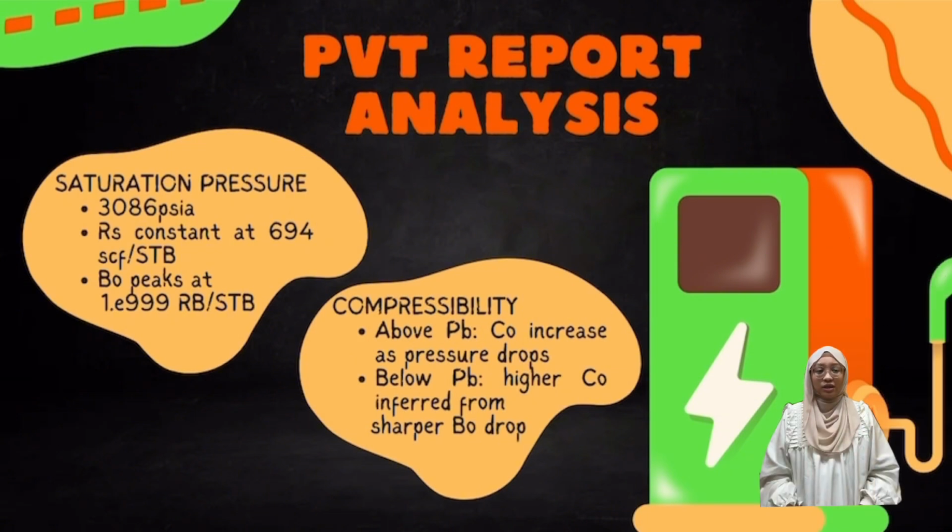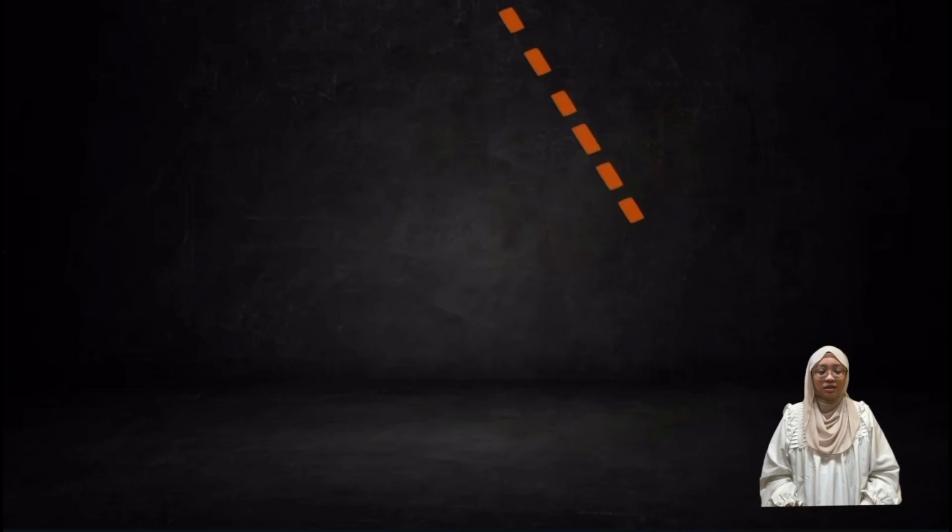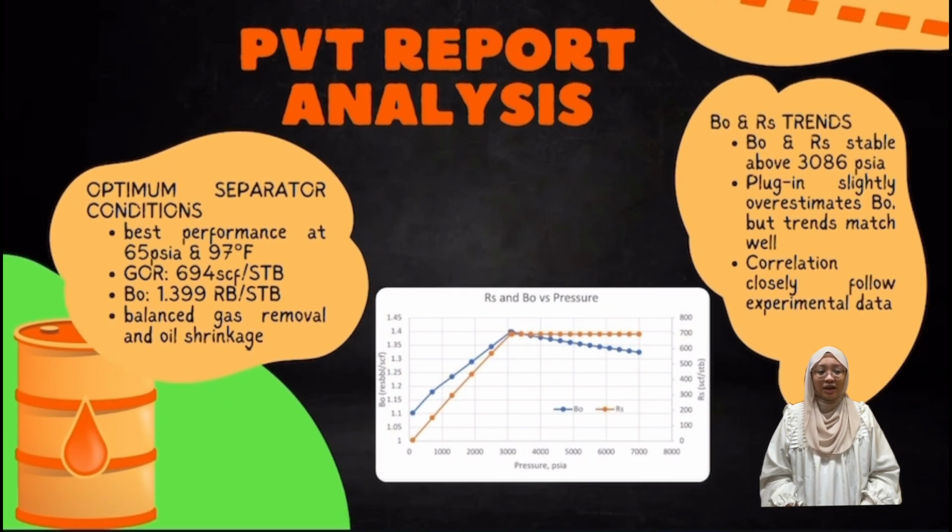For optimum separator conditions, it maximized oil recovery while maintaining stable fluid properties. According to the test results, the best performance was achieved at 65 psia and 97 degrees Fahrenheit, with a GOR of 674 SCF/STB and a BO of 1.399 RB/STB. This pressure gave the highest liquid yield while maintaining reservoir gas content. The API gravity remained stable, and this setting gave the best balance between gas removal and oil shrinkage. Hence, we identify 65 psia as the optimum separator pressure.